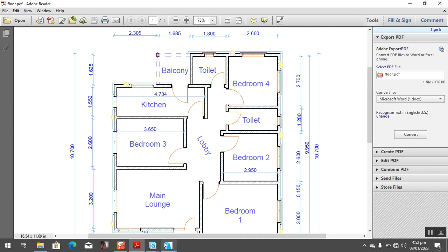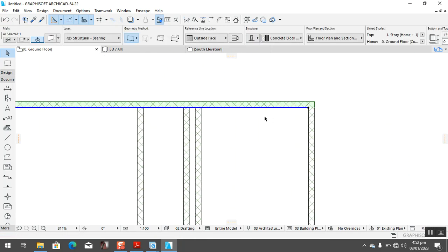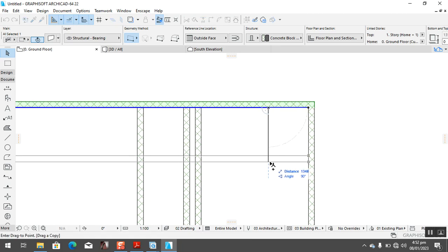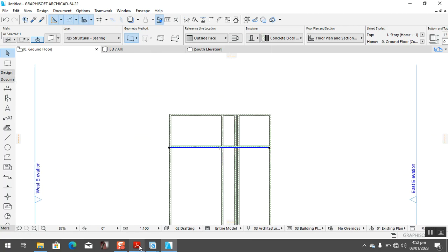This 2.7 meter. Let's go 2.7 meter. We start from here. Okay, 2.7. Adding your block wall is going to be 2.850. So you copy the same method. You drag. You put your 2.850. Okay. One room done. Let's look for the next wall.